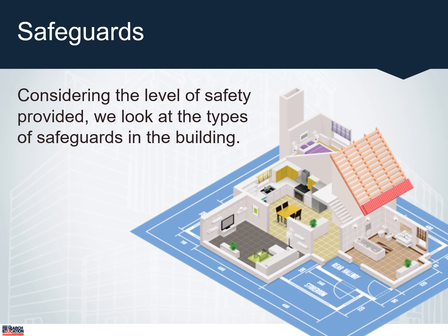Are portable fire extinguishers provided? Fire extinguishers give occupants a chance to extinguish a fire while it is still small, many times avoiding major fires. How many exits are provided, and what's the exit width that's provided? The more exits, the wider the exits, the greater the opportunity for people to escape an emergency, thus reducing the risk. However, the exits need to have adequate separation to be able to serve all of the occupants of the building. If exits are too few, too narrow, or consolidated in one area, the risk would be greater.